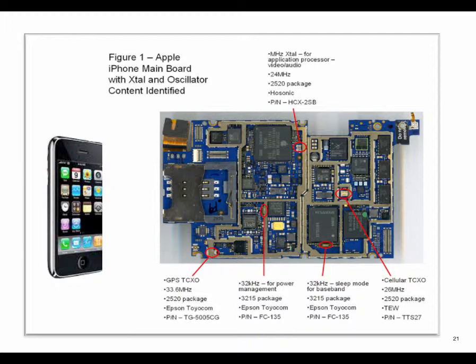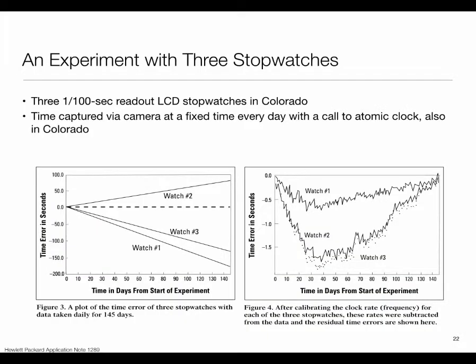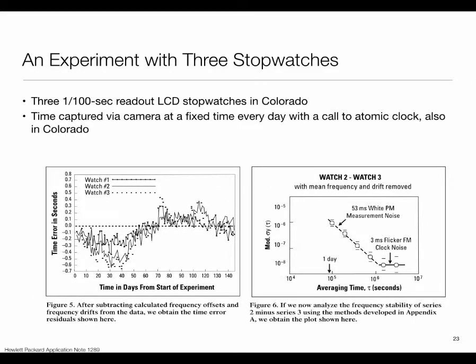These things cost more money and they burn more power. Essentially what they internally do is they have a temperature sensor, and by some careful calibration, they constantly keep correcting the frequency, so that in effect they get more stability than one would otherwise have. So one could certainly design these systems using TCXOs and get something more stable, still not enough for all the applications, but better than just using a plain one.